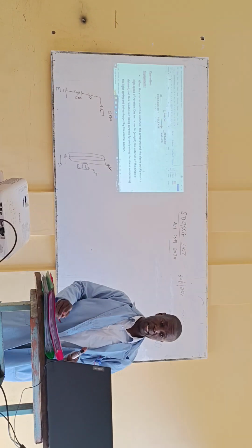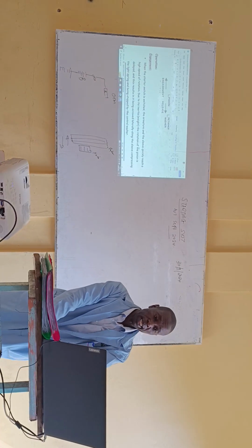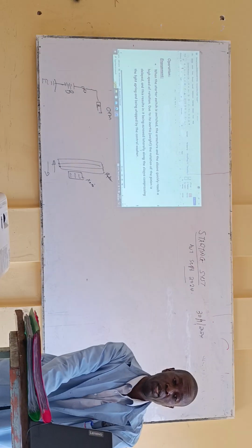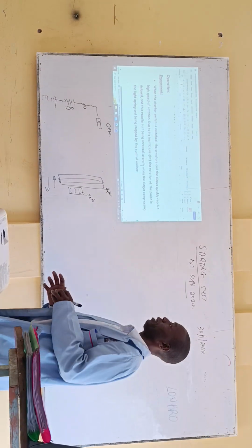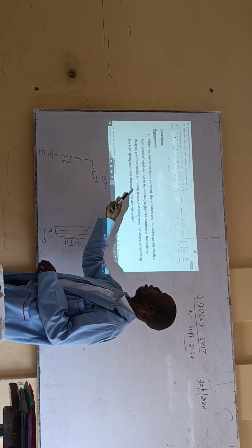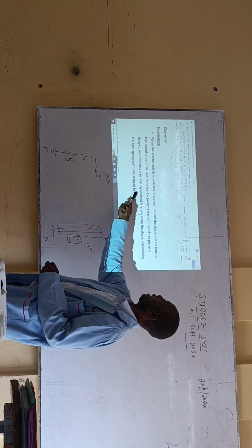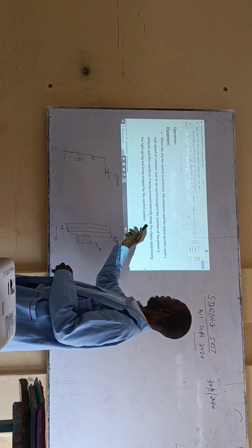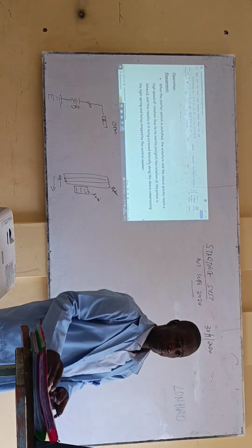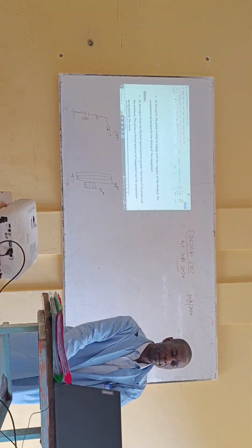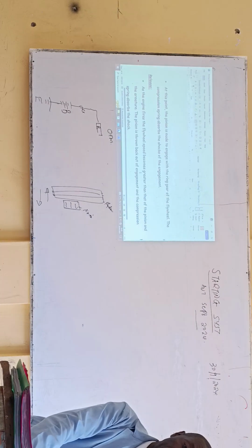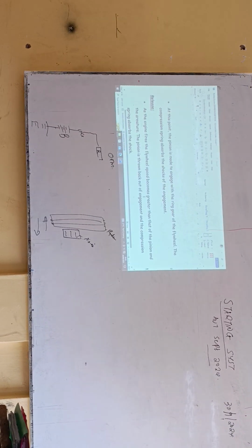So what happens on the engagement side, as I've already pointed out, is that when the starter switch is switched on, the armature and the sleeve quickly reach a high speed of rotation. Due to its weight, the pinion's rotation is delayed, and this results in it being screwed laterally along the sleeve, compressing the light spring and being stopped by the control washer. Then, number two, at this point the pinion engages with the ring gear of the flywheel, and the compression spring absorbs the shock of engagement.